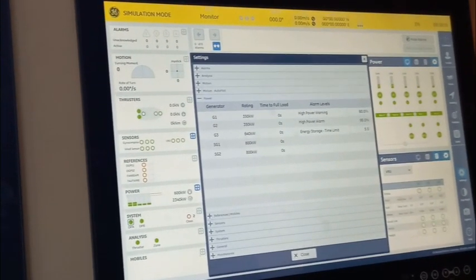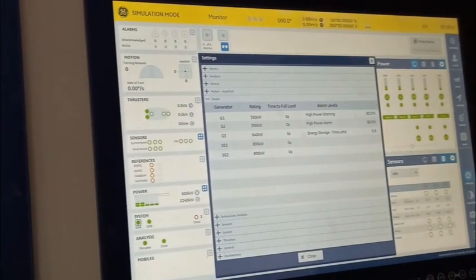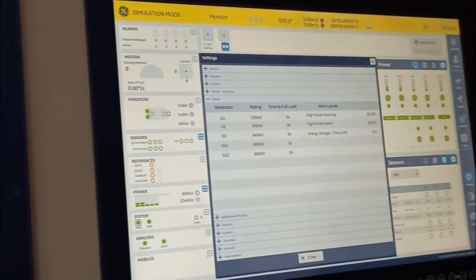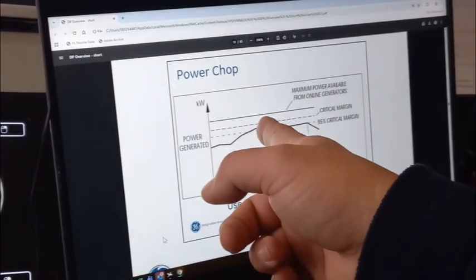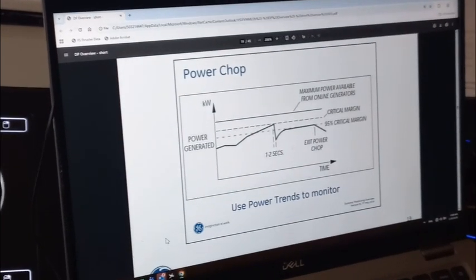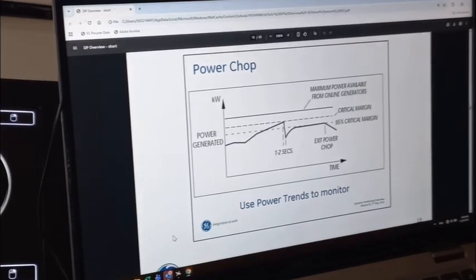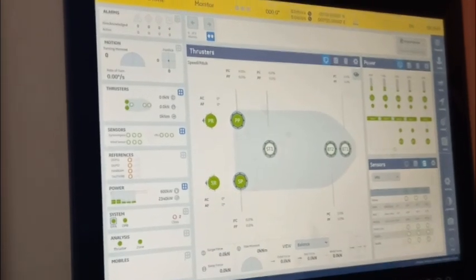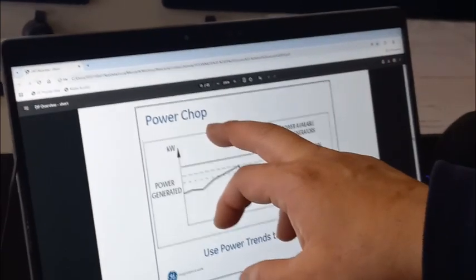I have one question. Is the power used actually what they're using on the main? Yes, because in Kongsberg, when it reaches 95%, the software within the DP code will choke the thruster demand. Let's say for your vessel. It's not power management, it's a function called power choke within the DP code.